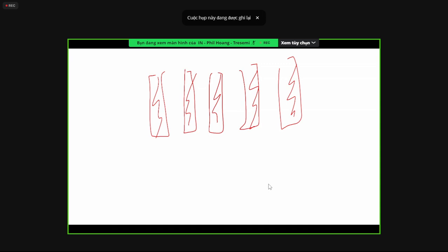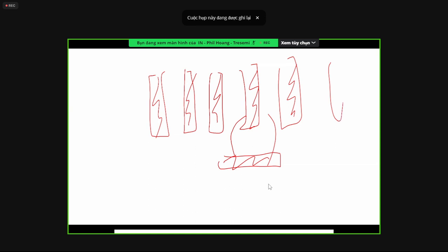For example, if your poly is vertical and you have another poly that is horizontal here, the presence of this poly relative to the other poly will affect how the shape is formed in real life, right? In real life, it's not going to be rectangular like this, because you're etching.